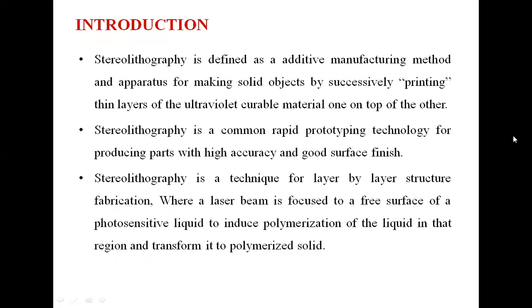Stereolithography is defined as an additive manufacturing method and apparatus for making solid objects by successively printing thin layers of the ultraviolet curable material one on top of the other. Stereolithography is a common rapid prototyping technology for producing parts with high accuracy and good surface finish.